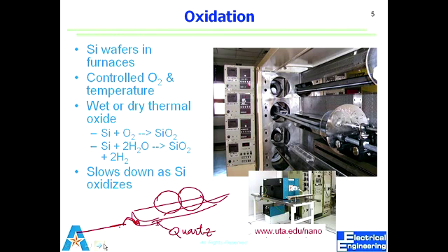There are notches here, so we match the notch, and there are notches at the bottom. So we put the wafer upright into that boat, and we put them in line, and then we push the boat with, again, a glass rod type thing, which has this kind of hook, and here we push this into the tube.